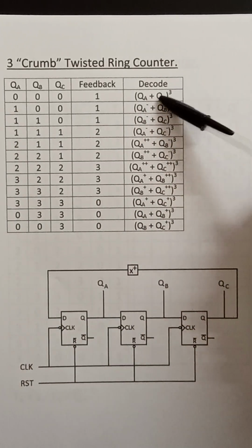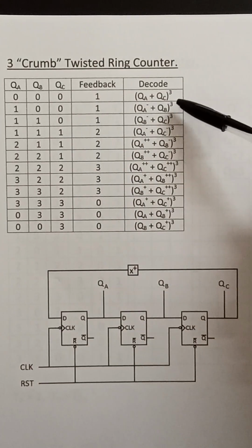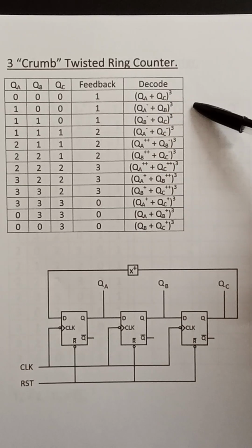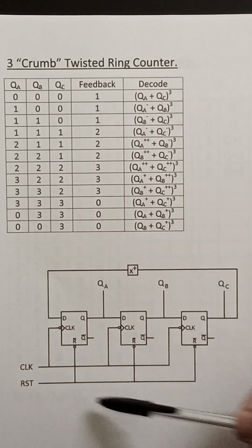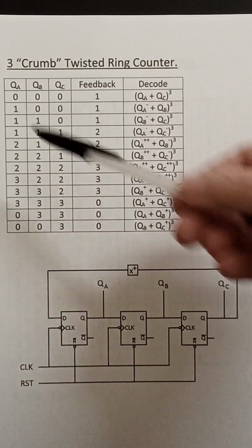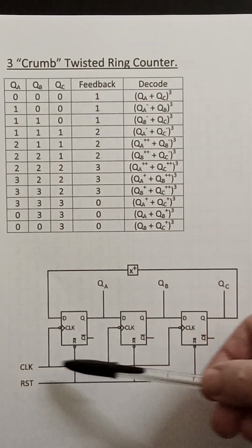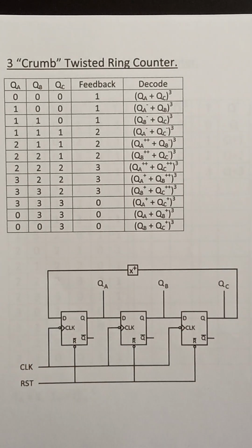So that would be a 0 at this line here, and that would make it a 3 on the output of the x3 function. So it's a 3 on this line only and a 0 everywhere else. Right. So here, same circuit, reset all the flip-flops to make it 0, and then common clock for synchronous clock.